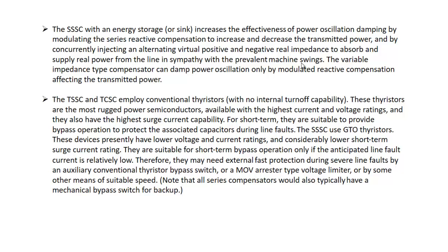Or it supplies electrical power in that case. So the load that has to come from the generator is relieved. When that is relieved, the difference between the electrical power and mechanical power will be reduced, and again the oscillation will be damped.